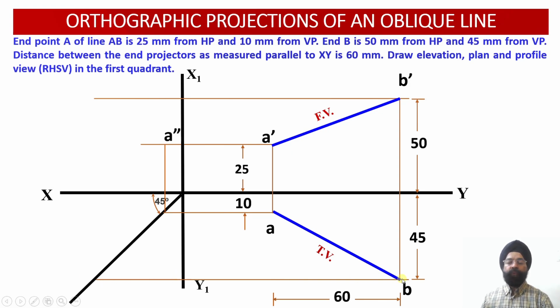What we are going to do from point B, once again, is draw a horizontal projector line and extend it till it intersects with the transfer line. Wherever this horizontal projector drawn from point B of the plan intersects with the transfer line, we have obtained a point corresponding to point B on the transfer line, and you can check this distance. This is also 45 millimeter, and this distance is also 45 millimeter. So this vertical distance in the top view projection has been translated into the horizontal distance, that is the distance from the vertical plane, as 45 millimeter in the profile plane projection over here.